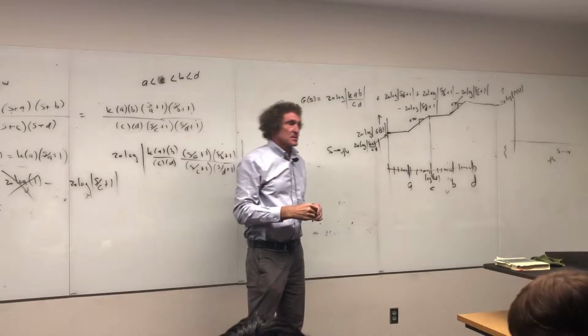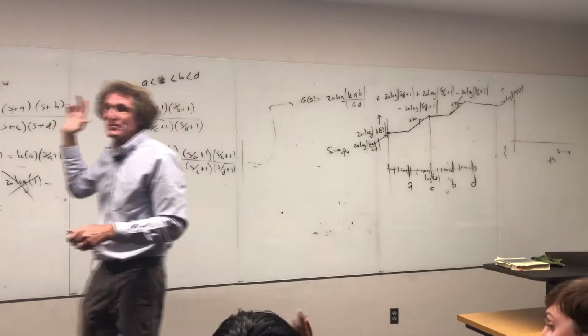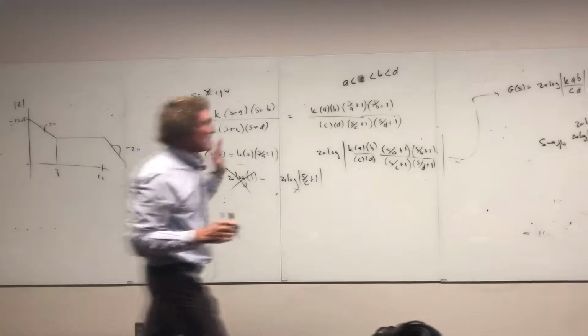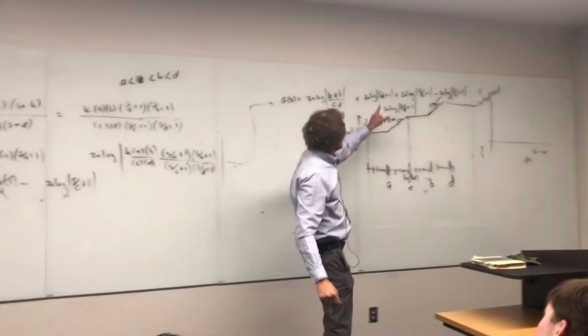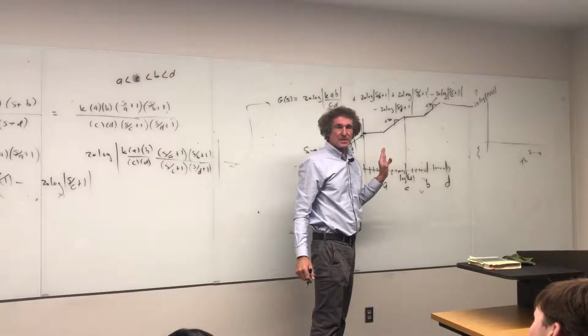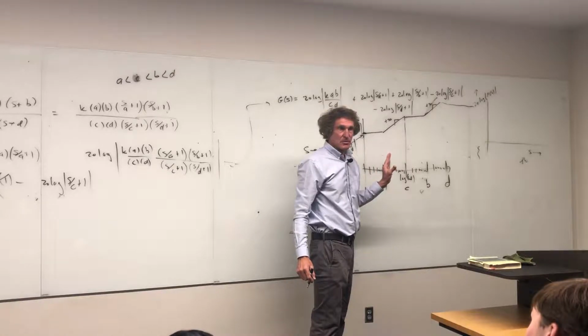Now, when you construct, how many understand what I've shown you here? This is a very rough way of explaining it, but it hits all the important aspects of Bode plots that people mess up. Most of the time, they forget to do this. They forget to scale everything so it's plus 1. That's the biggest problem with Bode plots most people have.